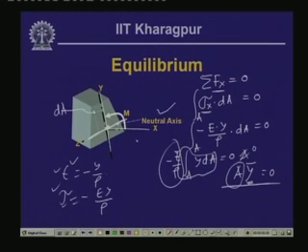So, in the cross section, we have a point where the strain and the stress are 0, and they vary linearly over the entire depth of the beam. We will have a variation something like this, wherein we have 0 strain or 0 stress over here, and here we will have strain and the corresponding stresses. This gives us the variation of the strain and the stress.